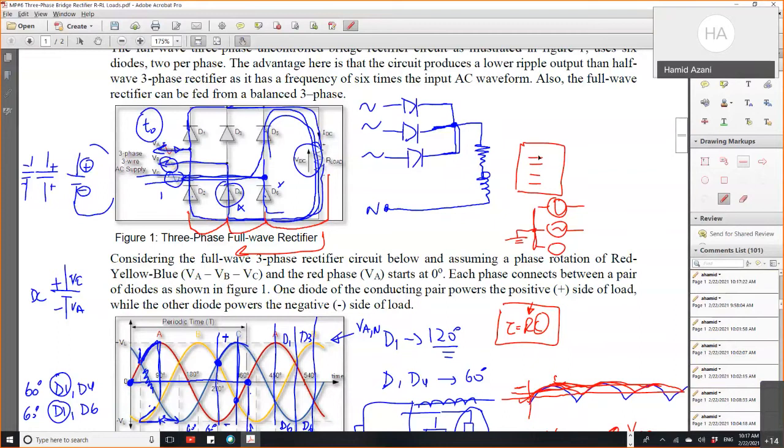For the diodes also, this rectifier, you will find one ready-made, but I think it's useful if you build this one by yourself. The source and the wiring by yourself, you will learn more. For the ready-made one, it's already made inside. You just have to enter parameters and that's it.